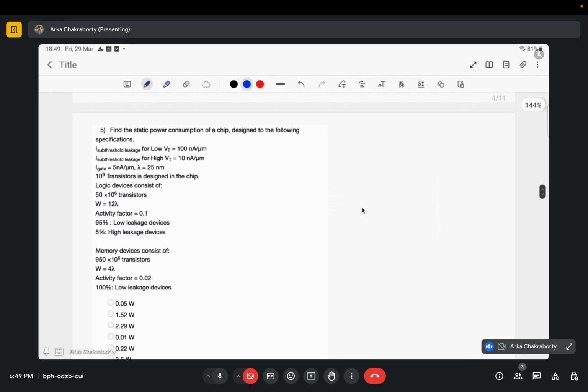Okay, let's move to the next question, question number 5. What has been given: find the static power consumption of a chip designed to the following specification. I subthreshold leakage for low VT is given, I subthreshold leakage for high VT is given, I gate is given, my lambda is given, and 10 to the power 9 transistors are used to design the chip, out of which 15 times 10 to the power 6 transistors are logic devices with W equals 12 lambda, activity factor of 0.1. Activity factor is not required for static power, it is required only for switching power or dynamic power. And it has been mentioned that 95% of the logic devices are low leakage devices, and 5% of the logic devices are high leakage devices.